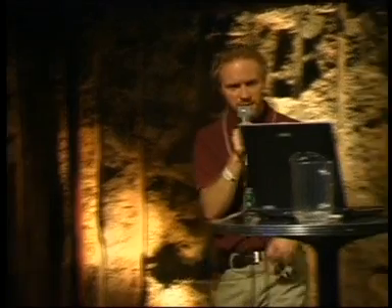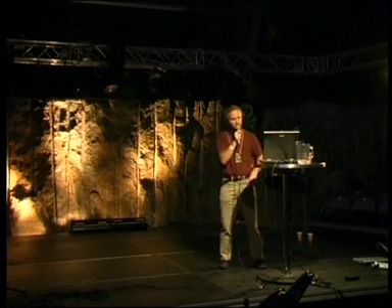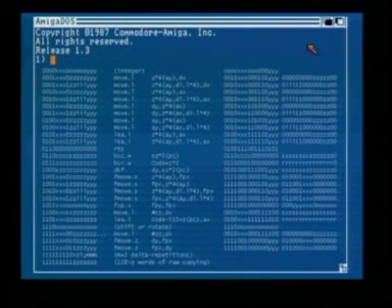And there's also the decrease loop instructions, which are normally 4 bytes, but are reduced to 2 bytes here again. Of course it's a bit fewer bits for the offsets, but again this is usually sufficient.